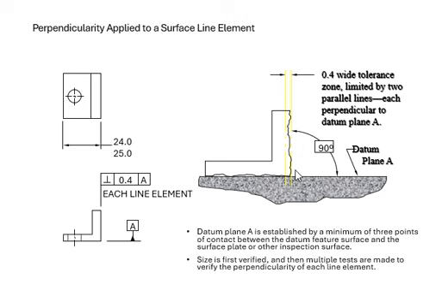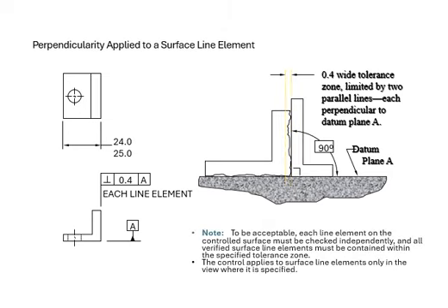And our parallel lines in your exaggerated diagram, we can see it. And this is your 0.4, because it's set here in your control frame. We do the same thing. Your gauge, your surface, your high points, at least you need 3. Why? Because of your primary datum. Don't forget these things, please. I don't want to repeat it again and again.